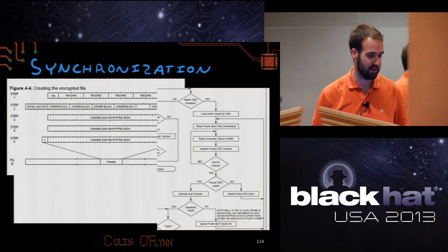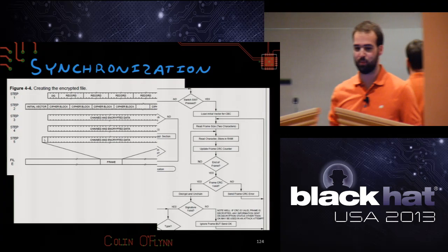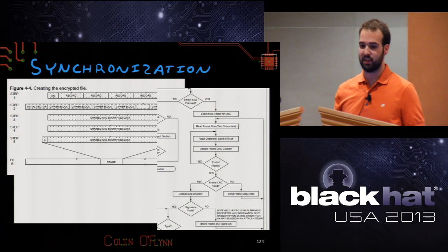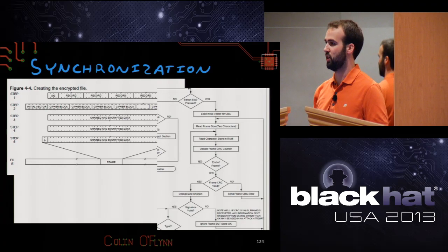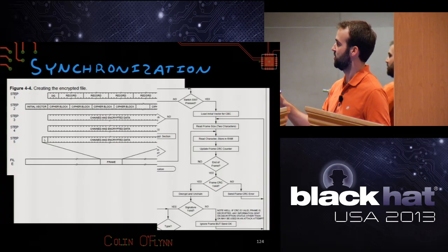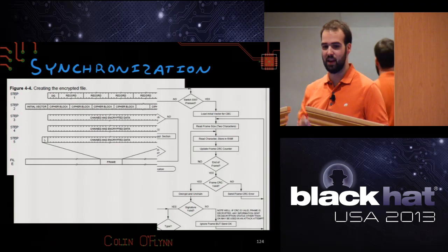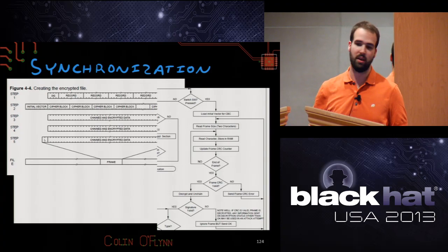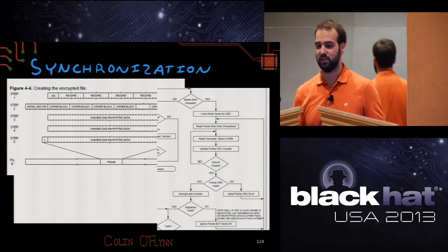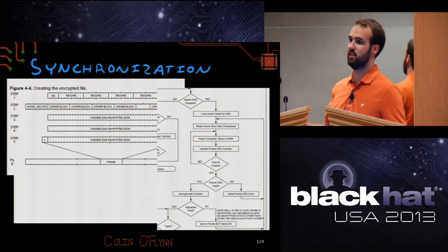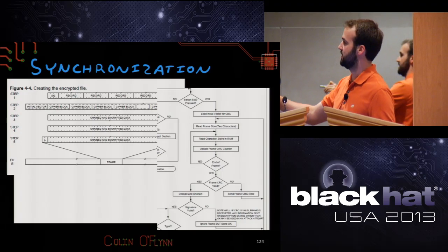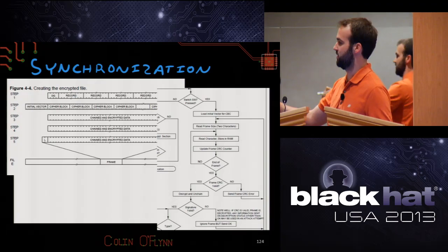So for example, this is pulled from an app note directly, and they're telling you here's how you make an encrypted bootloader. You take your file and chunk it into frames. Each frame has a bunch of encryption plus a CRC for detecting errors. And then you just send it to the device. If the device receives a valid frame, valid meaning it has a CRC and there were no transmission errors, it will then decrypt it, and then it checks the signature.